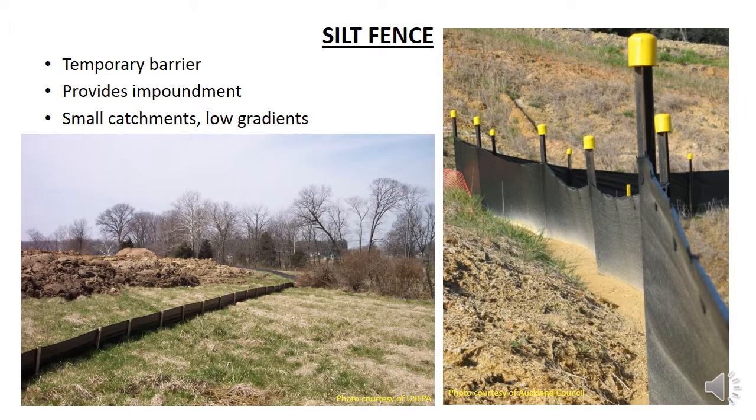Another sediment control measure is called a silt fence. Silt fences consist of a geotextile that stop the sediment particles but let water flow through. They are a temporary barrier and can only service a limited area of land. If too much water stacks up behind it, the silt fence is liable to break and let the sediment through.